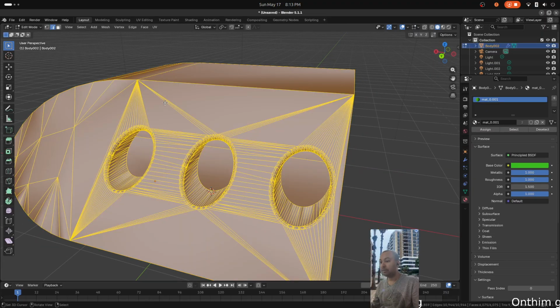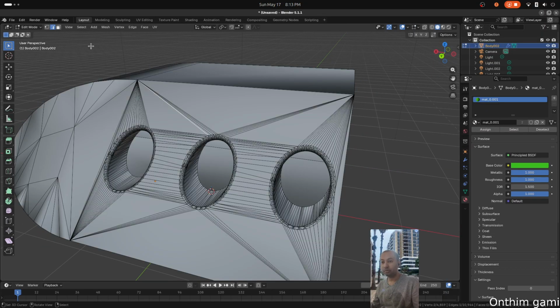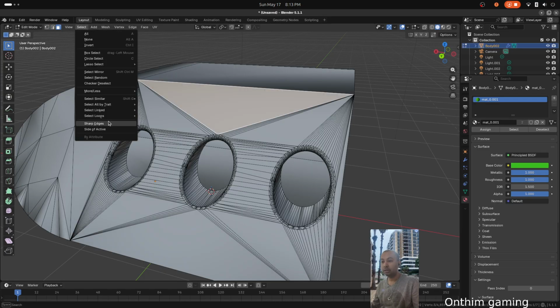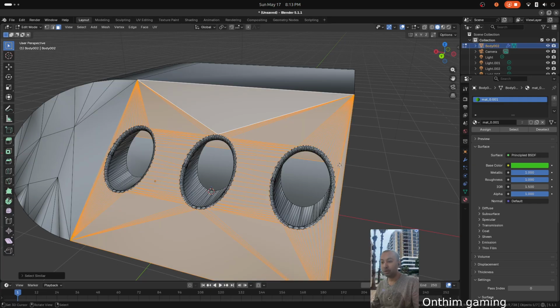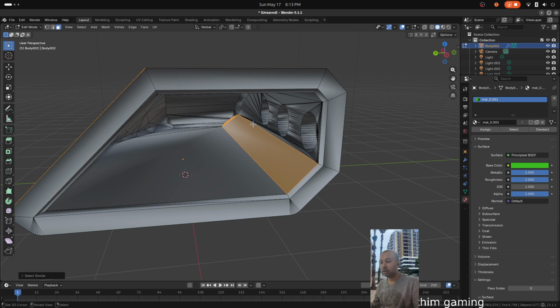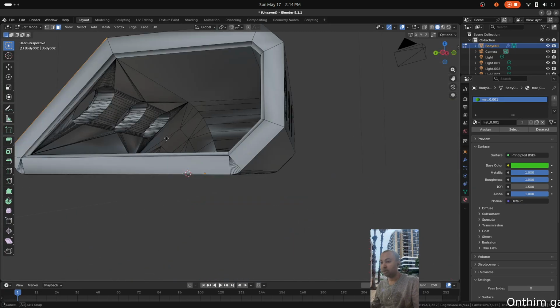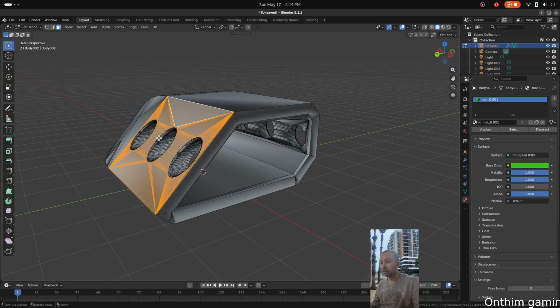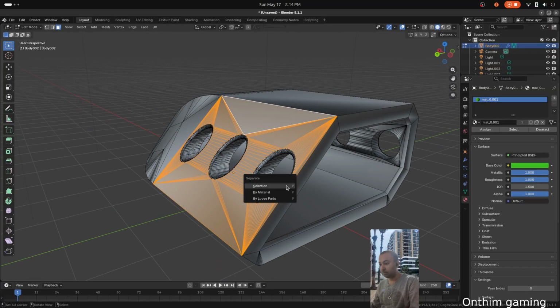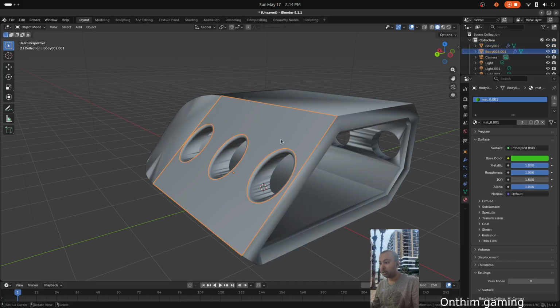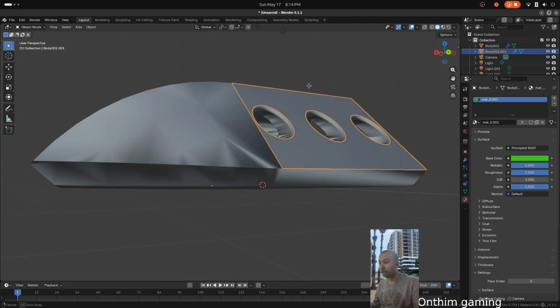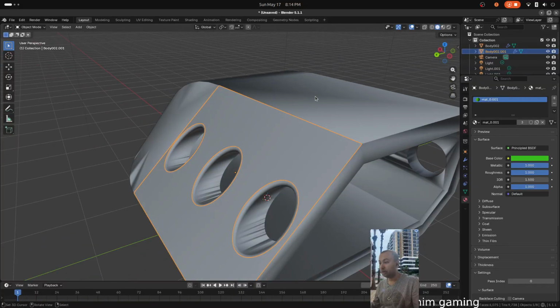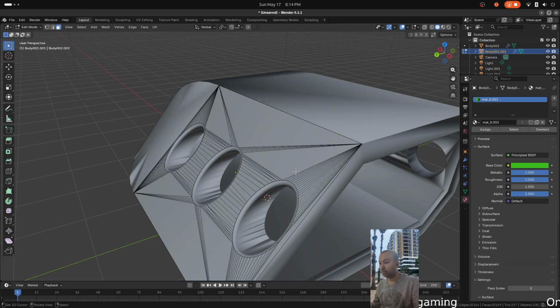And again, we can do the same thing for this face. Let's try to do it. Select one, select similar by normal, and you can see that also has it. So we can deselect those using C and the middle mouse button, so that those are deselected, and we're gonna separate this. P to separate selection, and you can see as soon as you separate, it becomes very clean because it's not interpolating the normals from the main body.